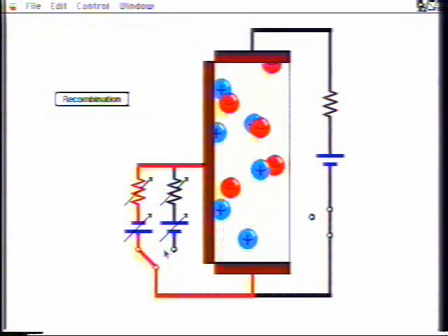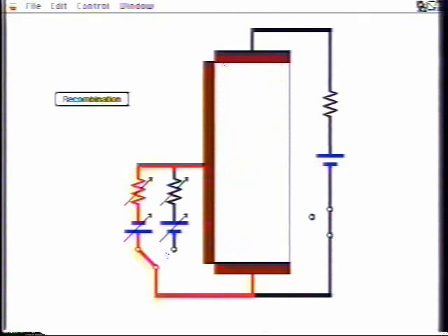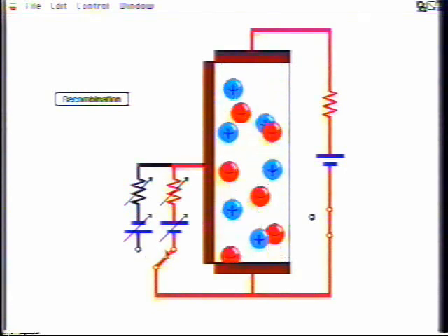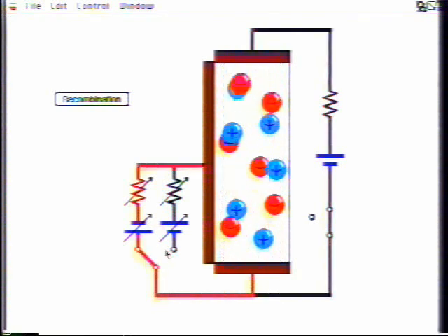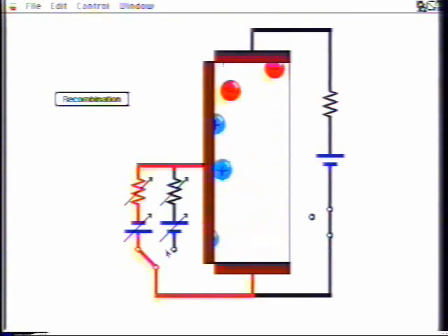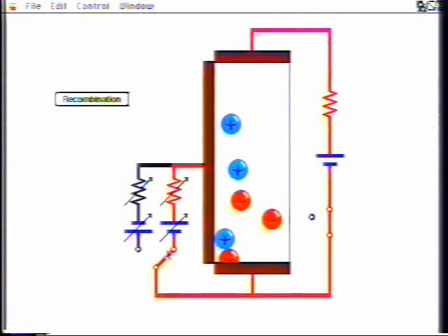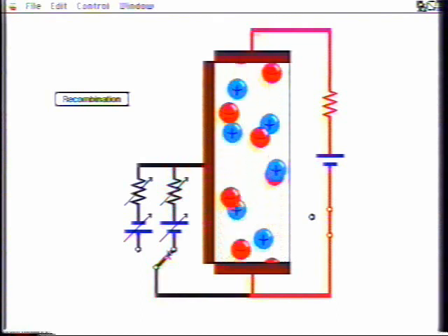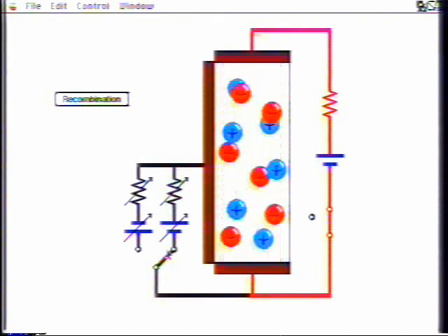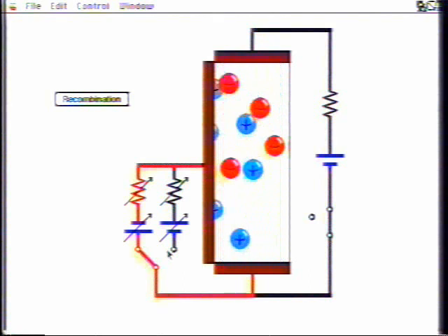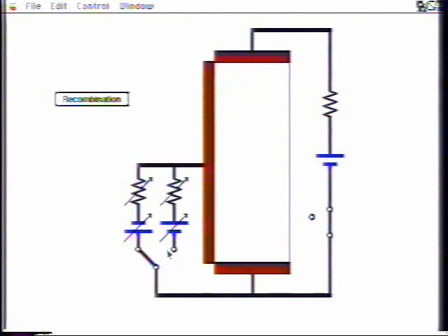Output current is controlled by input charge. Input current only flows when the controlling charge is being changed. Externally, the base emitter terminals behave as a capacitance, known as the storage or diffusion capacitance. Positive base current charges up the diffusion capacitance, turning the collector switch on. Negative base current discharges the diffusion capacitance, turning the collector switch off.